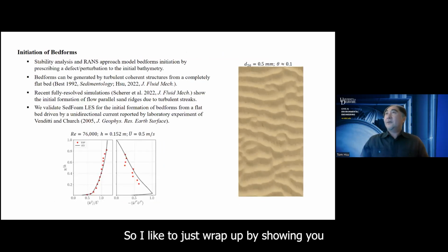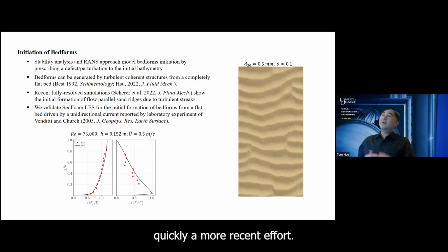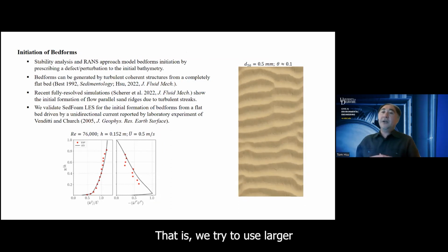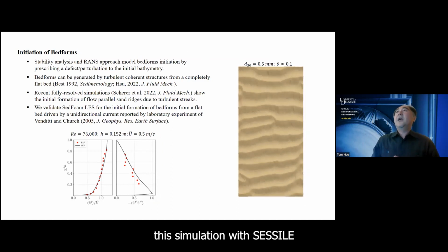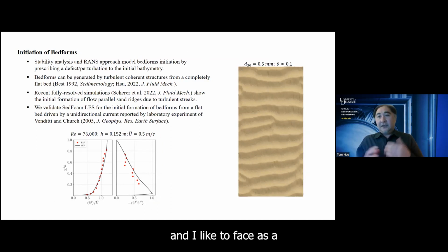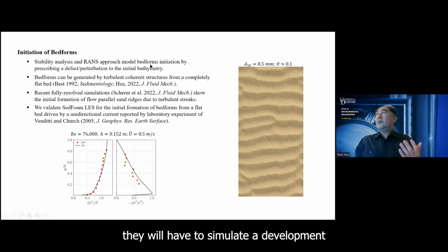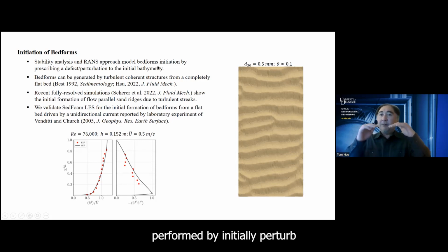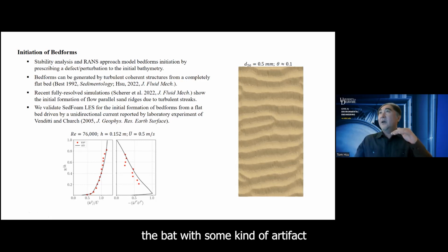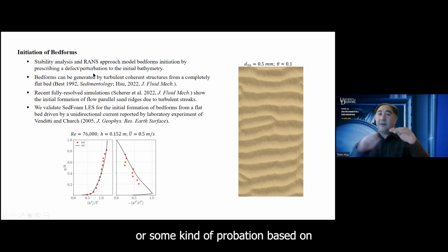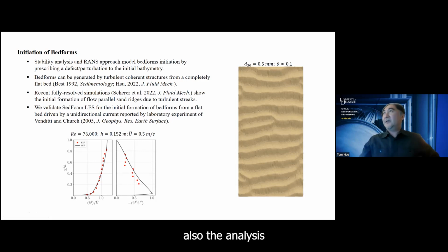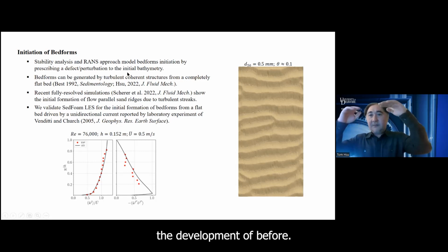Okay, so I'd like to just wrap up by showing you quickly a more recent effort. That is, we try to use large eddy simulation with SedFoam to study the initiation of bed form. I like to phrase it as a chicken and egg problem, right? Typically, if you look at people who study bed form, they use stability analysis or RANS models, but usually they have to simulate the development of bed form by initially perturbing the bed with some kind of defect or perturbation based on some stability analysis, so that they can start to see the development of bed form.